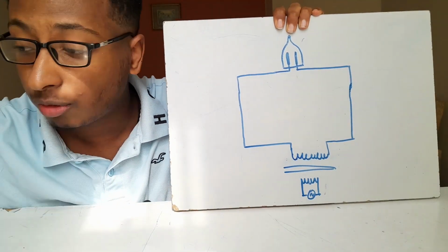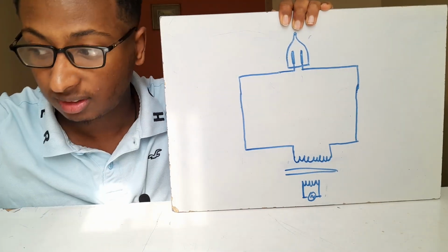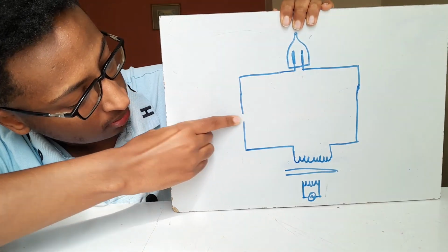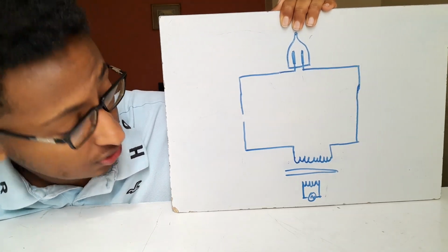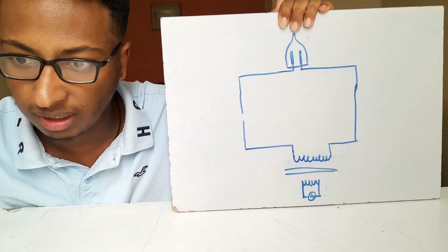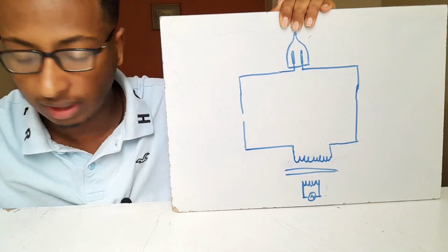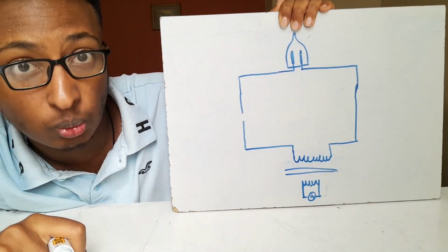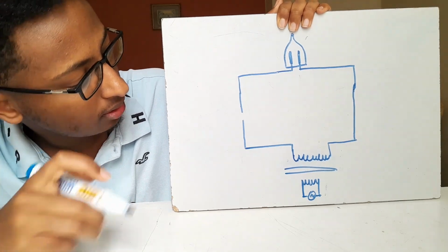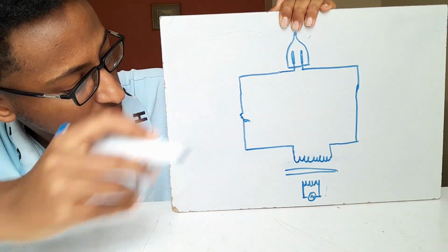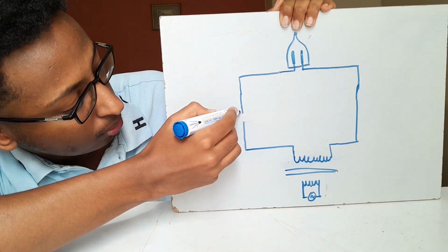But if we try to open the circuit, just like a switch, if we create a gap like this, depending on the voltage that this transformer puts out, if it's high enough, for example 90,000 or 100,000, the moment you try to disconnect this circuit, a huge arc will close the circuit, creating a spark through this gap.